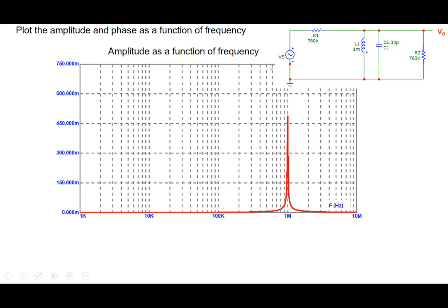If you think of it as a sinusoid as an input, this sinusoid is trying to go through this particular circuit and emerge at the output. What the circuit is doing is severely attenuating 1 kilohertz, 10 kilohertz, 100 kilohertz. It's not allowing those signals to pass through, right? The amplitude of V0 is very small. Similarly, if I were to do 100 megahertz, that also would have come out close to 0, a small value here. So similarly, high frequency signals are also being filtered out.